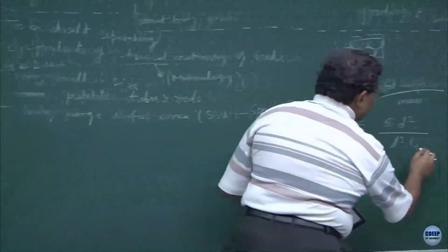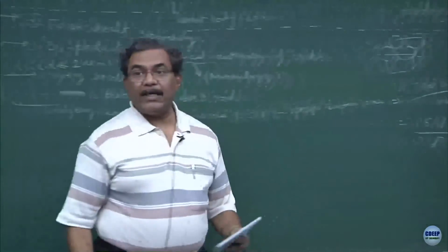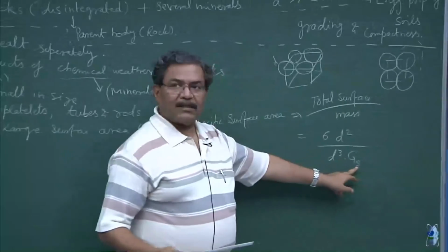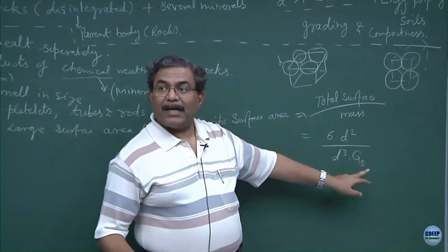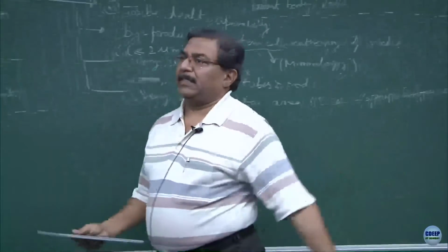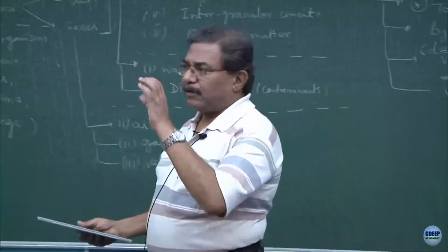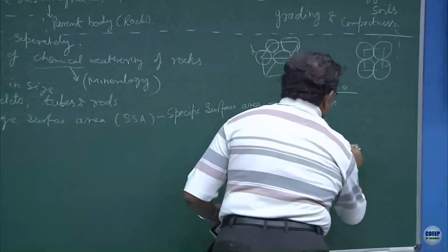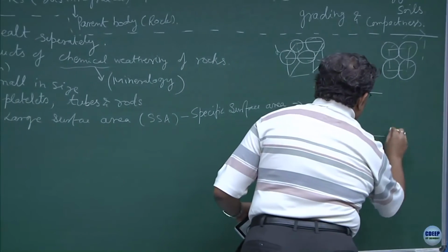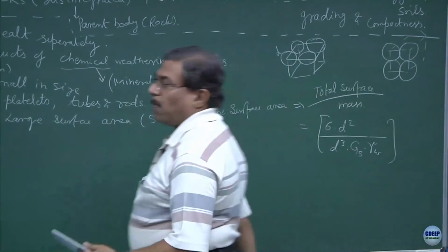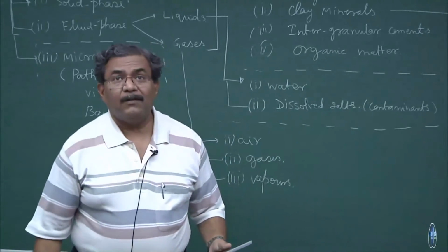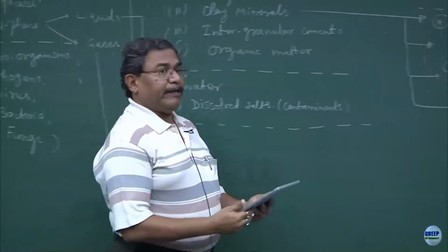To define the specific gravity of the skeleton of the soils or minerals, we will use the prefix GS, but after this discussion, I will not use GS ever, for the sake of simplicity. Clear? So G is the specific gravity of the minerals. This multiplied by gamma W. What is gamma W? This is the unit weight.